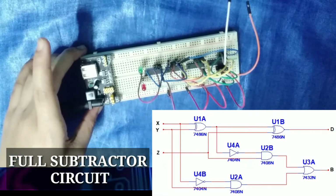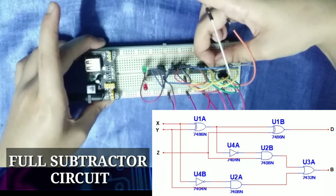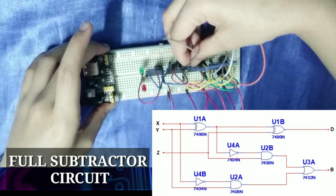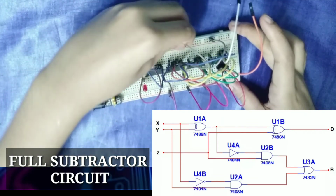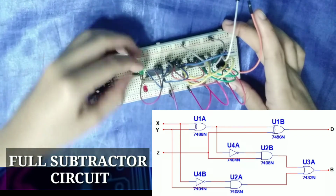And of course, do not forget to ground all of your ICs. In total, it will also be 4 grounding wires, okay, connected to the 7th pin of each of the IC. Okay, it's important that we ground our components to make sure that it will be working properly.